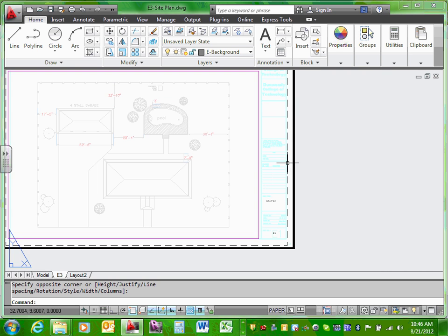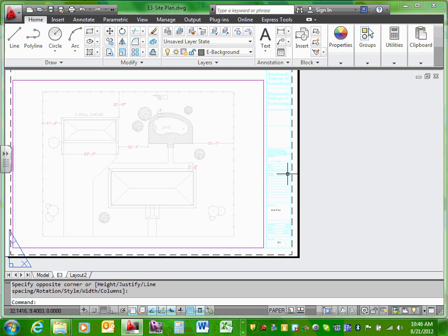You guys, some of you probably are not familiar with that. In the title block itself, everything is going to be in the title block except two things. These two things are the sheet, every sheet is going to be a different sheet, right? And the name of the sheet. So when you build your title block later on, when we edit the title block, you're going to put all the information inside the title block, except two things. You have to go in every sheet and every file and put them in every file. These two things are the name of the sheet and the number of the sheet.